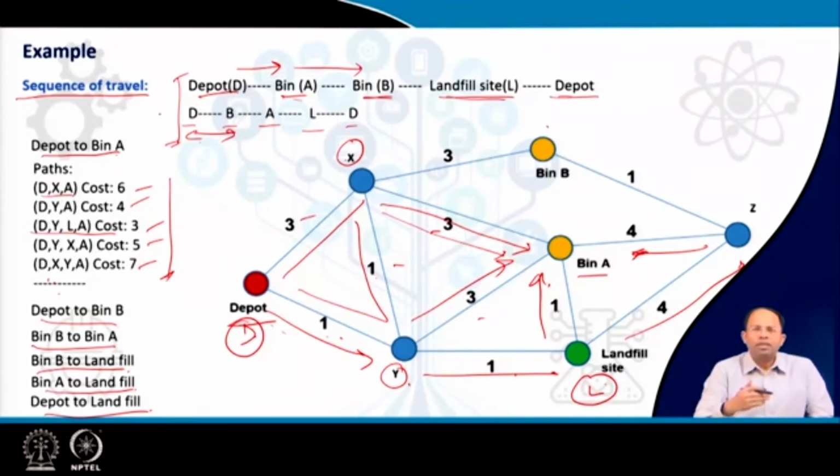So that means we are doing this in two stages. First, we are determining the shortest path between the points, and in the next stage, we are combining these shortest paths as per the sequence that we are proposing, or the order in which we will visit the sites, and then we will determine which one to choose. So this order of sites is also very important. Sometimes I can give a sequence which we have to follow, or sometimes if I say that the order should be as per the optimal value, then there has to be an algorithm or mathematical procedure so that we can find which order will give us the best possible result, or which sequence will be best for the vehicle to travel.